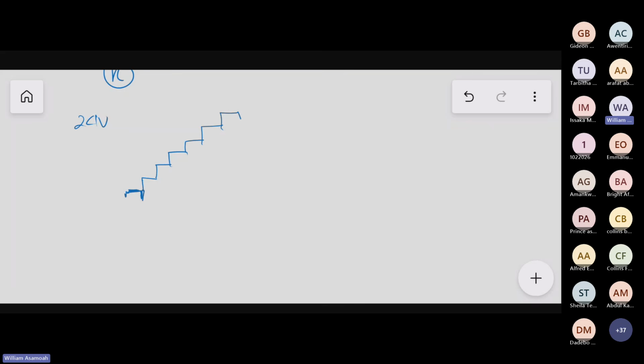In fact, soft starting is the most efficient way, other than all the other ones we are looking at. But unfortunately, it's quite complex because you need to write program code that will do that. You need to build advanced circuits that will be able to do that. So we usually don't like that. We go for the simpler methods, which are the passive soft starts, which use the NTC and the pre-charge resistors. But those are not very effective. So we like the active soft starting.